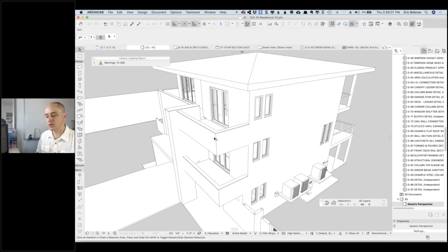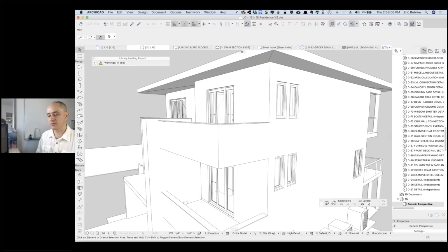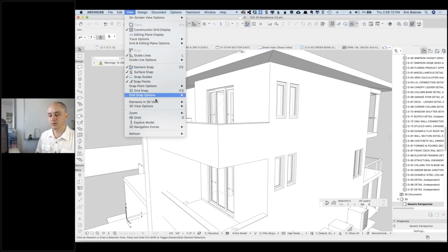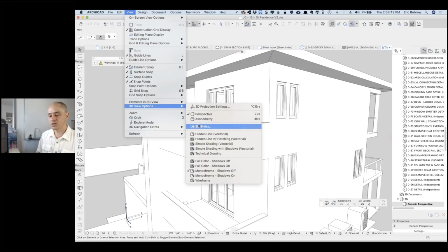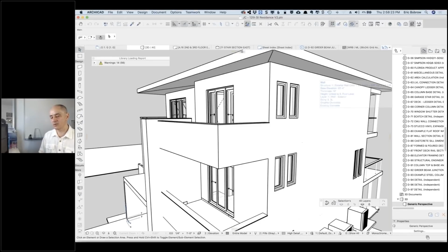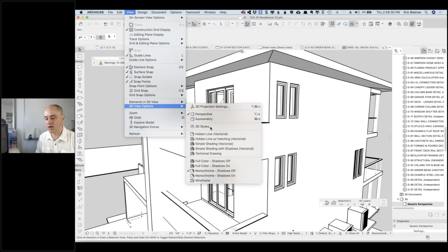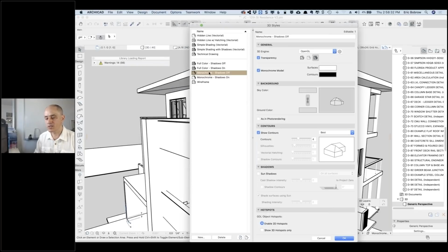You mentioned that you're having some challenges controlling line weights or something? Yes, yes. All right. Okay, so in OpenGL, the 3D styles command here has the ability to show contours best. You can make the contours heavier if you want, like this. So now it just stands out. I just changed that in the 3D styles dialog, and now this particular one is actually updated.